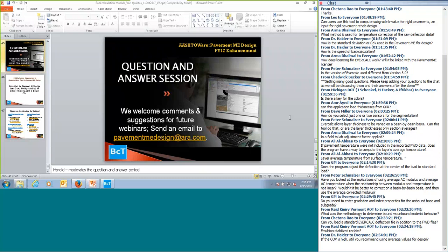If the thicknesses are highly variable, let's say from the GPR, ground penetrating radar study or field measurements, and a user wants to consider all those thickness differences, what that implies is you would need to have many more segments, because a segment as defined in EverCalc means we have the same layer structure, meaning layer type as well as layer thickness, within that segment.